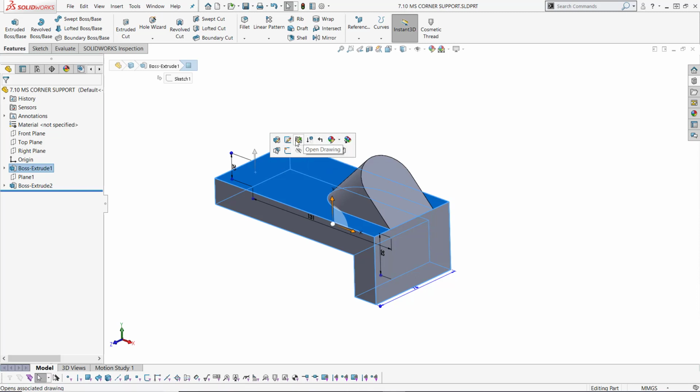Now one of the little tricks or problems that you could possibly fall into is if you want to create a sketch on a face of existing geometry. If you look at this icon here and you hover over it, you can see it's edit the sketch. It's editing the sketch that created that face, which would be the L-shaped sketch that we created on the front plane, which is a different plane to what this is on.